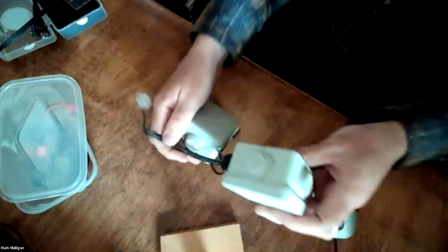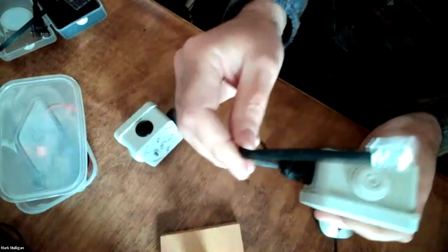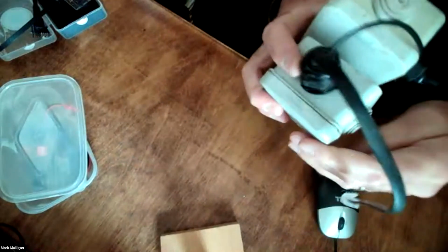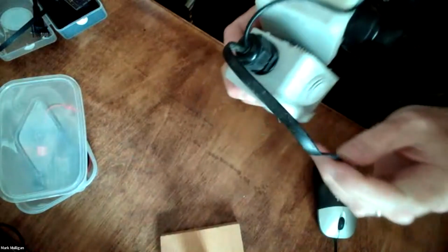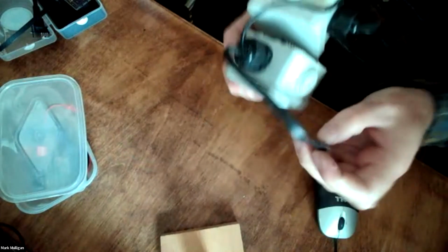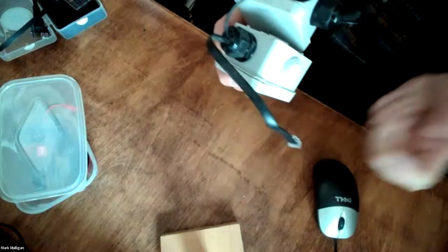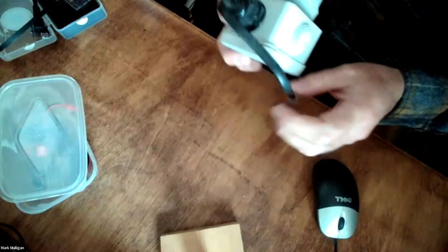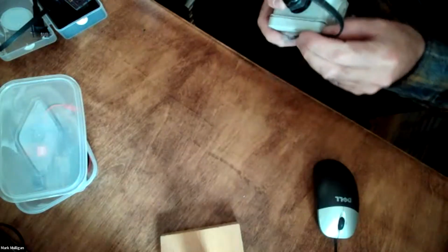Like all our sensors, if they're being put outside, we put them in waterproof enclosures. Usually they are like this, with again either a telephone cable or an Ethernet cable to connect the sensor into the main station. The challenge of building sensors is keeping the environment out of the sensor and out of the data logger. So most of our data loggers, we don't open the boxes at all for the years that they are in the field, because we go up to them with a mobile phone, we transfer the data that way. We don't open the boxes, because once the humid environment gets in, then that's not very good for your electronics.